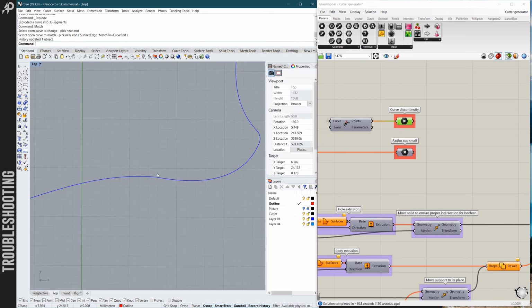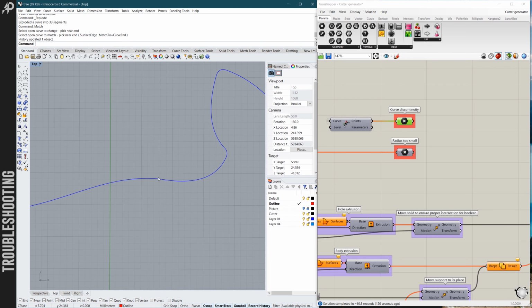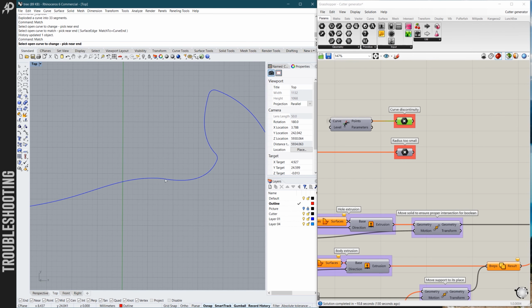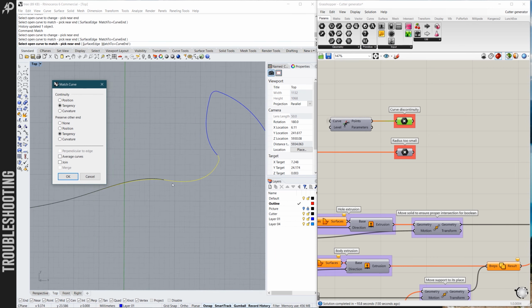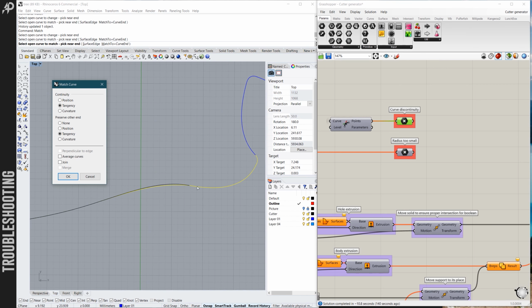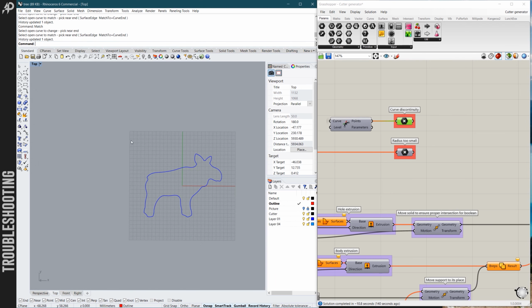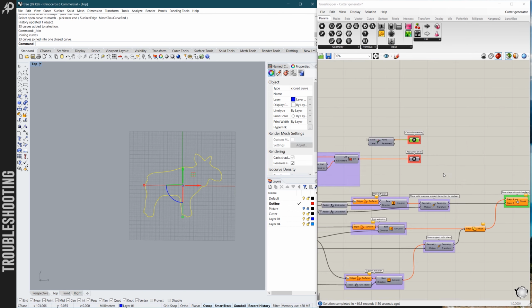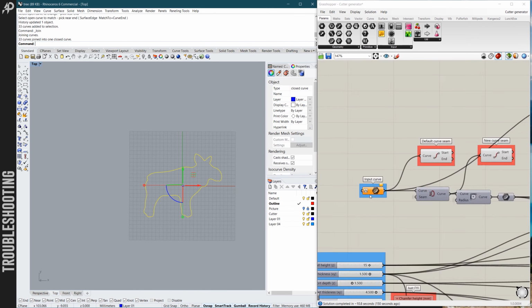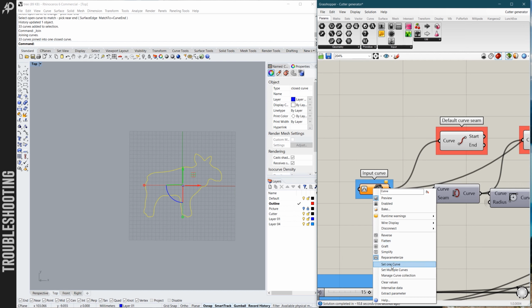And the other discontinuity was hidden somewhere here, so we just right-click, repeat the command. Consider which of these curves we want to change. Let's say the longer one. It changes the geometry a little, but we don't really care. Tangency, tangency, OK. Now we press Ctrl J during our outline again. Have to reinsert to Grasshopper.